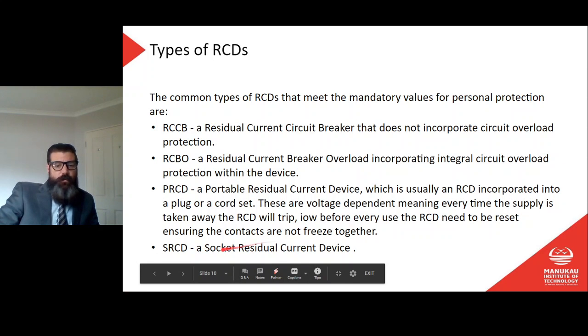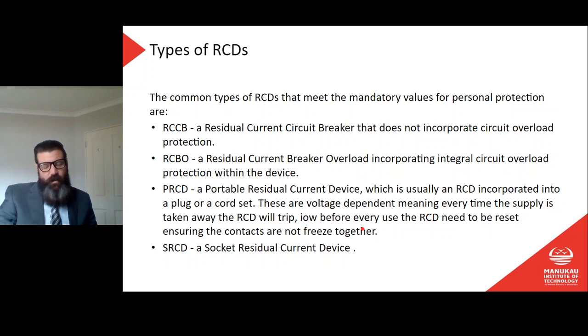SRCD, a socket residual current device. Again, they're far less common these days than they used to be. We've seen these, right? These are your socket outlet, generally in a bathroom. So these were probably pretty common in the 90s, maybe early 2000s, before it was a requirement that all socket outlets had to be protected by an RCD.